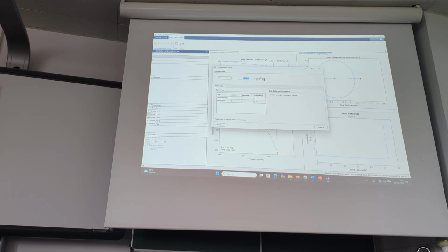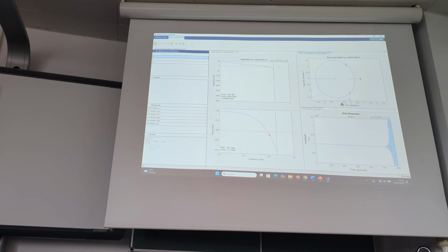In order to do that, I decrease the value for C. So when we see the poles already, now I grab one and push the conjugated complex pole pair into the unit circle, and then we see the step response to the reference step, and it's a damped oscillation with the sample time, 1.4 seconds.